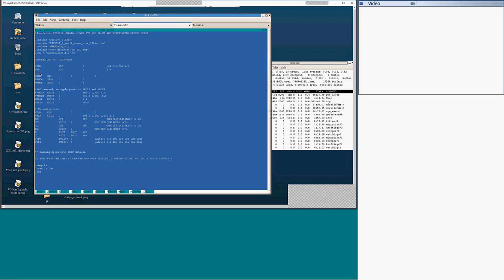And then we have to define supplies like GND, GNDA, GNDB. In the normal case you just say that this is global zero, but for InVar, a power supply should be defined as a voltage source between node 0 and a specifically named node, GNDA, VDD2P, VDD2N, and so on.